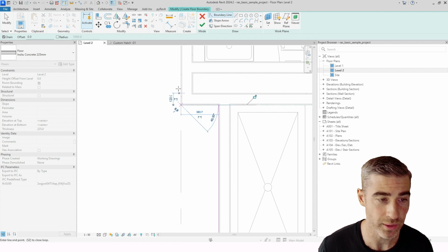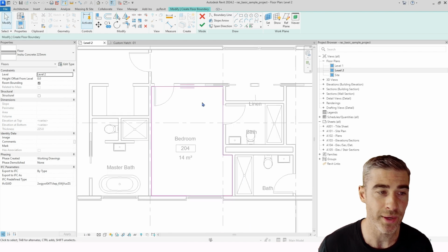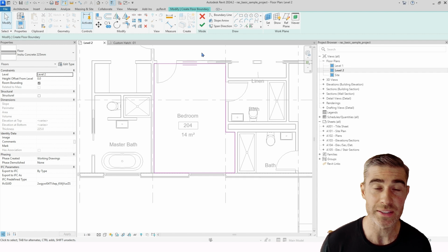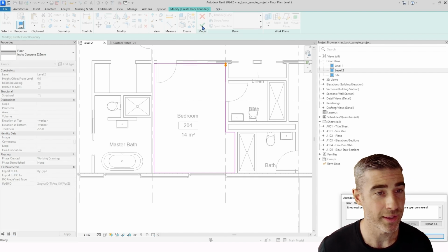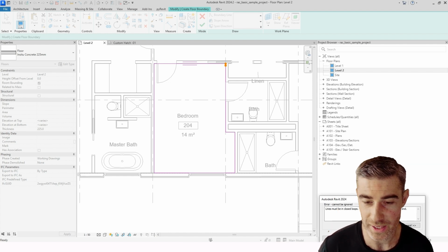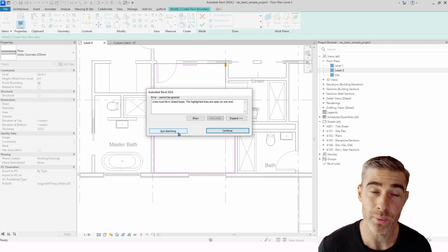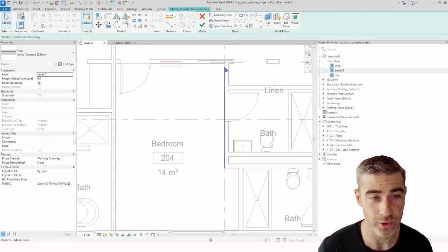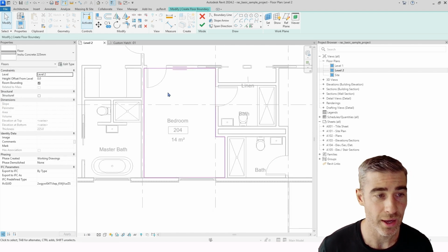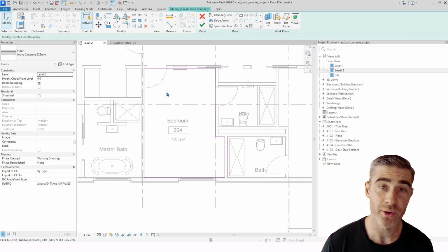So I think what I'll do here is I won't fully enclose it. I'll stop it shy, just as if I thought I had fully enclosed it and I'm ready, and I hit OK. If it's not fully enclosed, this is the note that you're going to get. It's going to say, the loop must be closed. So at this point, we don't want to quit sketching, but we want to hit Continue, and I want to fully enclose that.